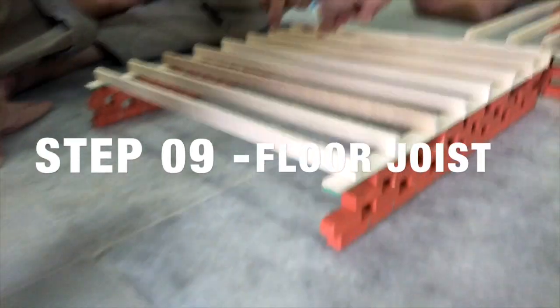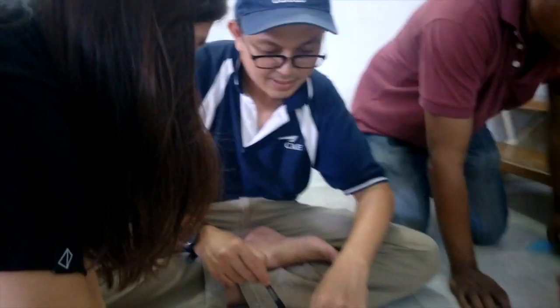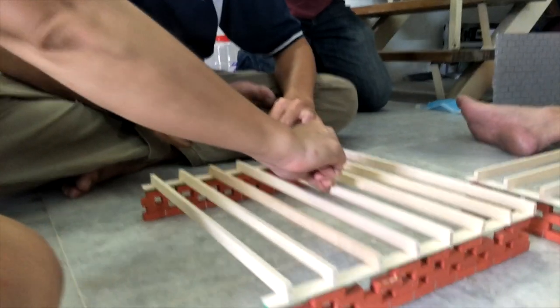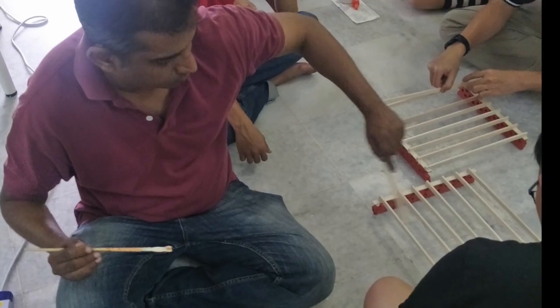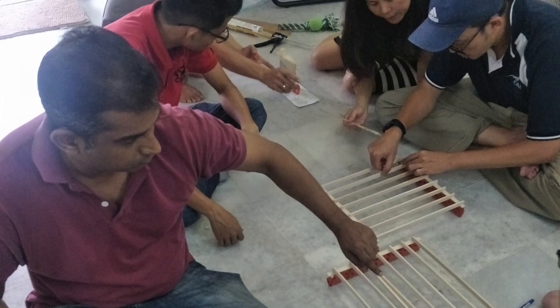Floor joist. The main function for floor joist is to provide support to the floorboard and finishes. Floor joist is a structural member used in framing to span an open space. For suspended timber ground floor, floor joist is rested on the wall plate. The end of the joist could be built into the wall or bedded on the wall plate. The size of the floor joist is determined by span between supports, total load, spacing, and quality of timber used. It is important to ensure the height level between the rested floor joist and the ground level is no less than 150 millimeter. On the working model, we are using 8 units of basswood strip. The floor joist is rested on the wall plate.